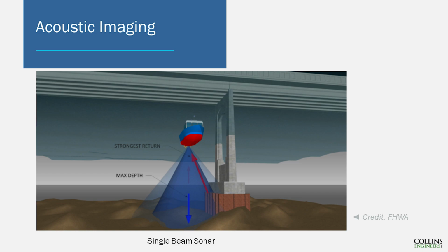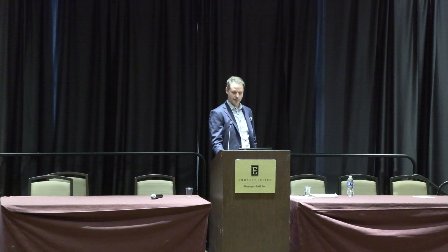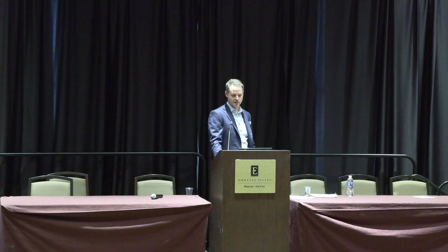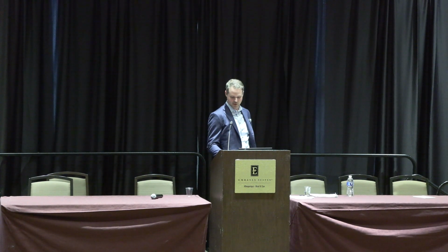If you don't know, sonar stands for sound navigation and ranging. This image here on the slide is what most of you probably think of when you think of sonar. It's a single beam of sound generated from the vessel that returns a depth reading like the fish finder in your boat. It measures the time the sound wave takes to bounce off of a target and return to the source. It typically produces a cone-shaped sound wave, and the pulse is strongest directly below the transducer, and it weakens as the angle from the central axis increases. So you're usually getting a return from what's directly below you, and you can get false returns from something on the edge, which is shown in this picture here.